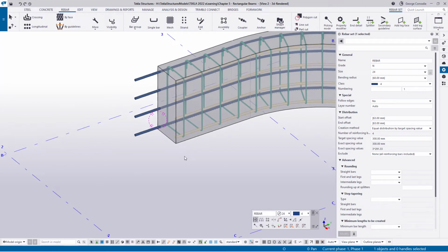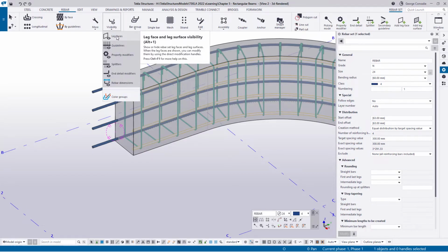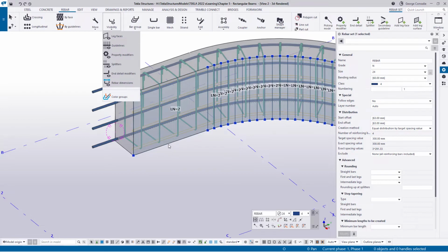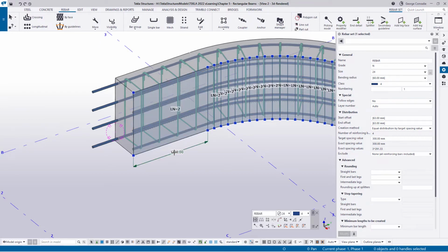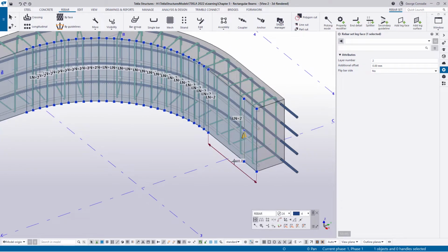And I need to stop right there because I want to show you the difference between the two methods that I'm going to be using right now. If I click faces here and over this one, I'm going to click this and say extend from this side. And then I want to extend by the 500. So I want to turn the 1200 into 1600 and actually physically extend the face here. I want to do the same here, and it's going to become clear in a minute why I'm doing this.